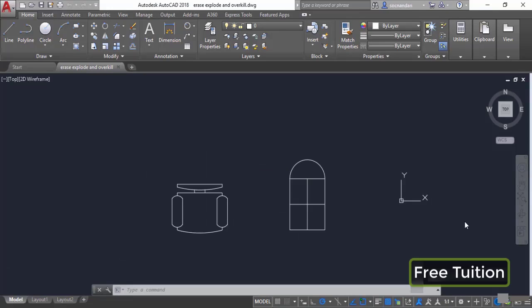In this video, I will tell you about erase, explode and overkill command of AutoCAD. So here we have these two geometries. In the first case, we have this as a block, and we'll learn about blocks later on in this course. But for now, just assume that a block is a single entity here, and it is made up of many different drawing objects which we have seen so far. We have this arc here, we have the line segment, and all of these objects combine together to make a single block. But in this case, we have this object made up of simple object. In this case, we have this rectangle, we have these line segments and an arc. So they are completely separate from each other.